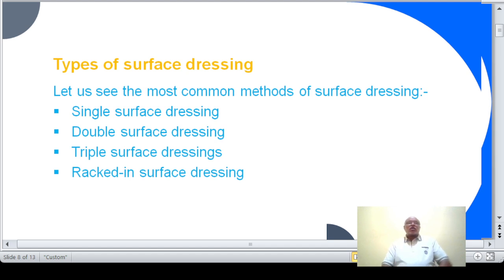When applied as a maintenance operation to an existing bitumen road surface, a single surface dressing can fulfill the function required of a maintenance reseal, namely waterproofing the road surface, arresting deterioration, and restoring skid resistance. A single surface dressing would not normally be used on a new road surface because of the risk that the film of bitumen will not give complete coverage.